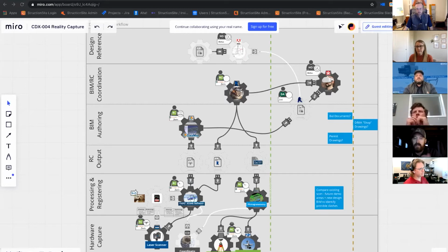Yeah, granted you got your scan, but is that wall a double wide brick wall? Does it have studs in it? Is it just a concrete wall with block? Nobody knows, right? The scanner is not going to tell you that. So there's some level of investigation that has to happen. But much to Blaine's point, the walls are or aren't straight up and down, but in my Revit file, they're going to be straight up and down, because it has to represent that in a 2D environment clearly, right?